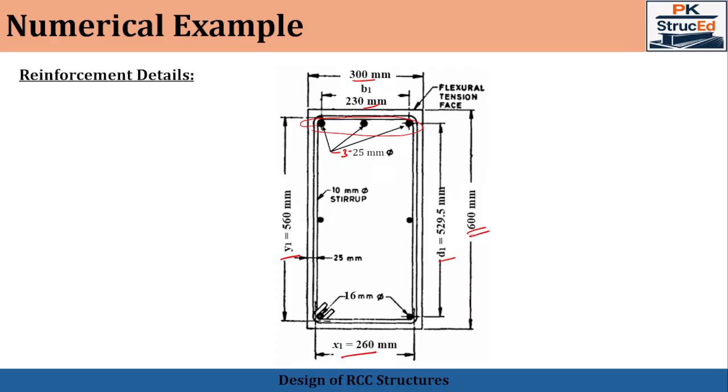So now let us summarize today's lecture, that is shear and torsion are critical failure modes. Torsion tends to amplify the shear stresses. IS 456 uses the concept of equivalent shear, and the design involves bending check, shear check, and the design of longitudinal as well as the transverse reinforcement. In addition, the proper detailing ensures safety, ductility as well as durability.